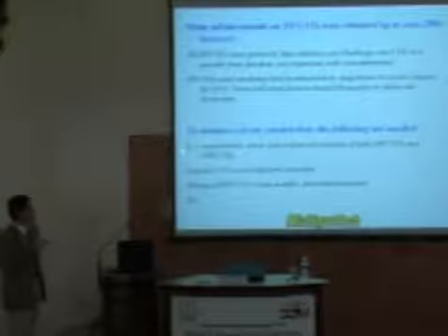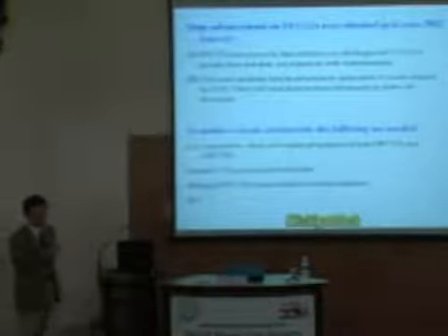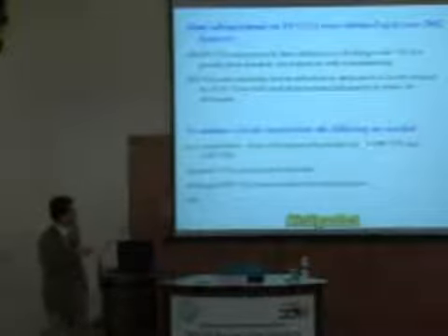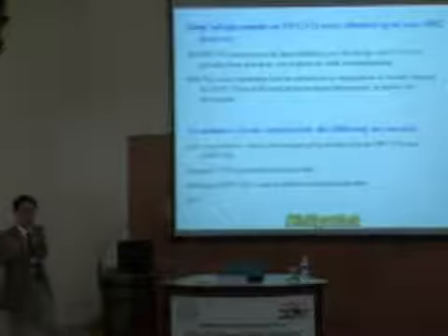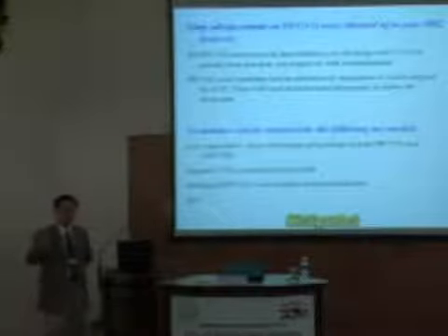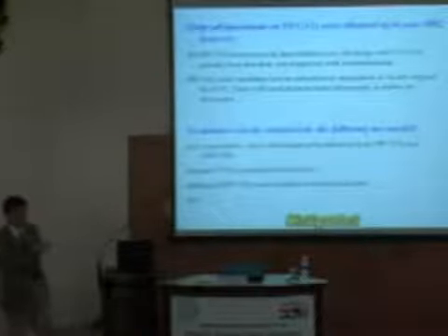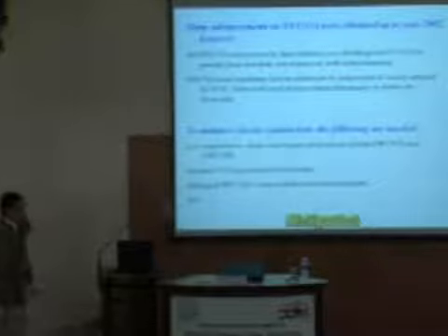So what I would like to say is that to enhance circuit construction in the future, some of these challenges must be overcome. For instance, you have to be able to achieve low temperature, clean, and organized synthesis of single wall nanotubes, as well as the multi-wall tubes, because in devices, you might need some conducting wire to bring your electrons from one point to another. And carbon nanotubes, multi-wall tubes, are just the right materials for this purpose.